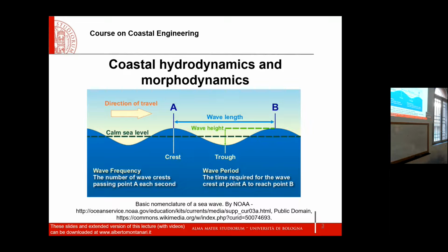Yes, I like this discussion, and let me emphasize one thing that you said: monodimensional. This is 1D, this is essential. What does it mean, 1D? It means that if you take a plane on the wave crest, crossing the wave perpendicularly to the sea bottom and perpendicular to the wave direction, then as the wave travels, this plane travels parallel to itself. As time passes, this plane travels forward and remains parallel to itself, which means that the wave is not bending.